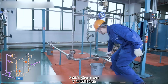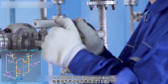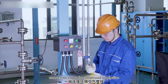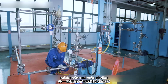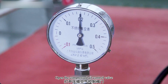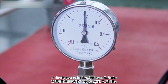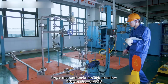Seventh, air tightness test. Check the valves of the pipeline to be tested for air tightness and close V6. Prepare a quick hose. Connect one end to the compressed air pipeline and the other end to the pipeline to be tested for air tightness. Open the compressed air control valve to slowly pressurize the pipeline to 0.2 megapascals. The pressure must not be too high or too low.